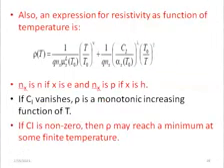And also the expression for the resistivity as a function of temperature, because we know whenever temperature increases, the breakage of bonds keeps on increasing also. So therefore temperature is a parameter that affects the resistivity, and that formula is given: rho of T equal to 1 over q n_x mu_x(T0) times (T over T0) raised to power gamma, plus this, where this q, everybody knows, is the charge of an electron, and n_x is either the concentration of holes or the concentration of electrons, because we put x here. That x can be hole and it can be electron.